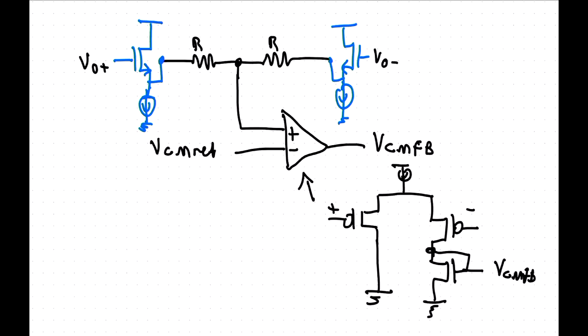And it doesn't matter if it's rippling? I thought that's why we really want high common mode rejection, and having our output ripple seems like a really bad thing. Yeah, but the output is the difference between the two. So if the output goes like that, it doesn't change the signal. It's the same reason that fully differential is good at rejecting noise coming in, because noise is often injected as a common mode.